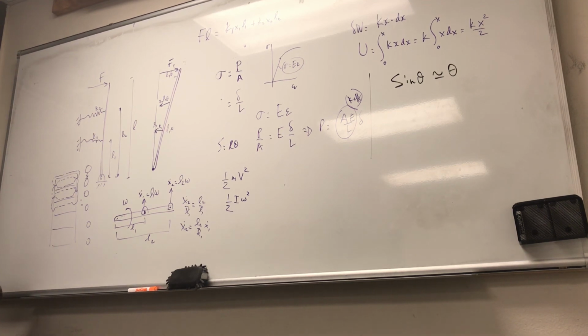You can have fluid flow around the piston in a cylinder, or fluid flow through an orifice. That's probably the one that is typically used, where you have a piston that's got a little hole in it. As you get a shock or something like that, you're forcing a fluid to go there. So that's why you're getting this resistance. It's not going to happen immediately, right?